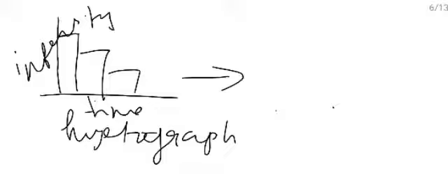Now we have the infiltration index or W index. This infiltration index takes into account only that amount of water which has infiltrated into the ground. Now this W index will include with it that amount of water which has infiltrated or penetrated into the ground, as well as interception losses, etc. So these are intensities only, meaning centimeter per hour or meter per second, like that. Okay, with per unit time.